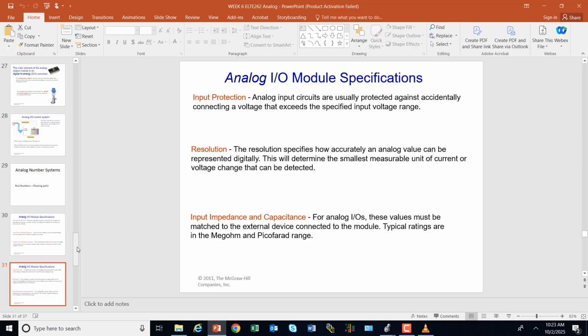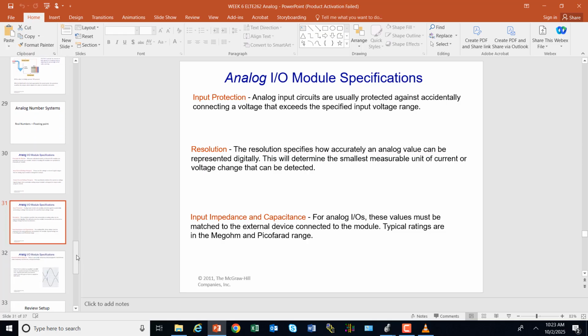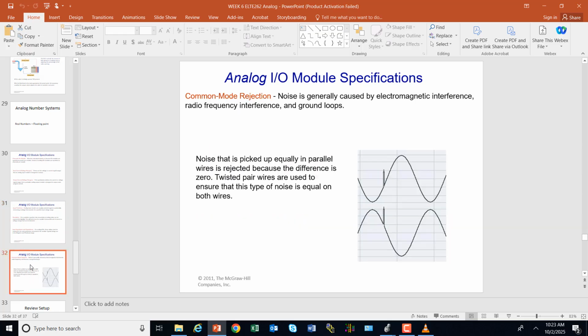So we can put in some offsets or some kind of calibration, I guess, a little bit, but really we need to get in there and calibrate our voltage supply to be sure that we get 0 to 10 volts, okay? But that's stuff that, if you were setting up and measuring analog, and it did matter that you needed exactly 0 to 10 volts, then you want to get in there and be sure that it's producing what you want, okay?